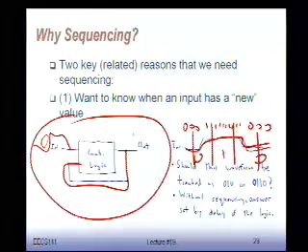So I'm going to have something that creates a time base. The time base typically is going to be your clock, but it doesn't have to be a clock. If I do a self-timed type of thing, remember the completion signal that I mentioned? It could be saying, hey, I'm done with my computation, go on to the next one. If I have something that helps me create order, like this comes before that, I'm already a lot better. That's what clocks do. It's a very simple way of creating a time base.